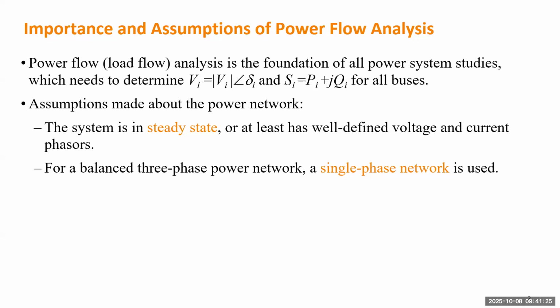Definitely you cannot pick just a single phase, because if you pick A, where the fault is added, phase B and C will be different. So there's a methodology called the sequence component method, which can decompose the system network into 3 fictitious networks. One network represents the balanced part, which is called the positive sequence network. The second is the unbalanced part, which is the negative sequence network. And the third one is called zero sequence, which you can think of as the sharing between the phases A, B, and C. The transformation from the 3-phase network A, B, and C to the sequence network is accurate.